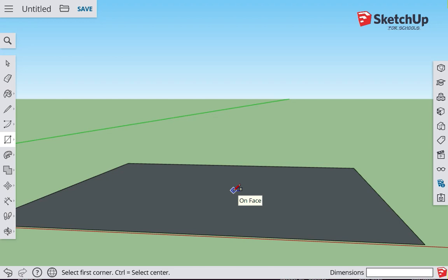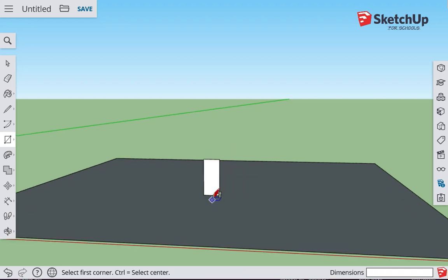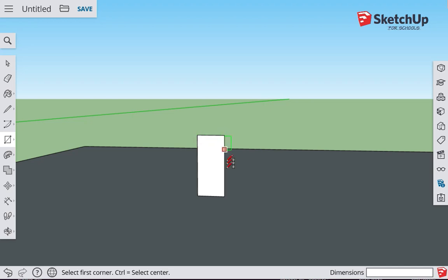Now the next thing we'll build is a rectangle on this. Switch to the line tool. We'll use rectangle. And that's still a line tool. Let's switch to rectangle. There we are. And I'm going to constrain this to be perpendicular or on the green plane. I'll put it right in the middle, and let's make this 40 by 90 millimeters. And that's going to be roughly the shape of half of our cup.